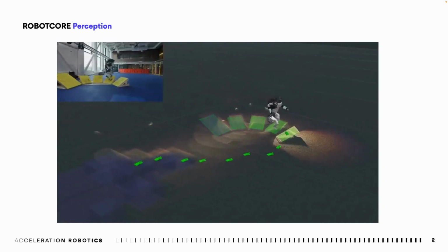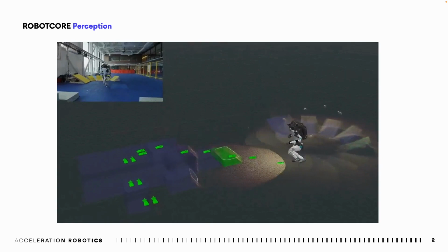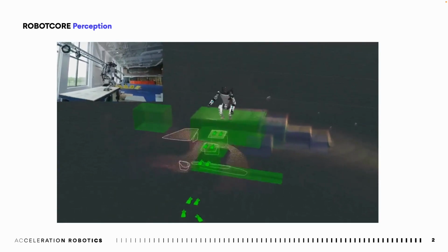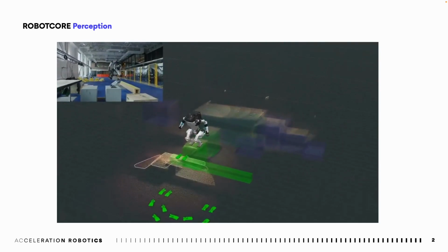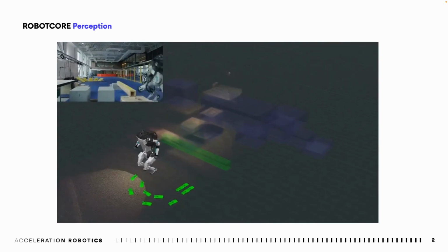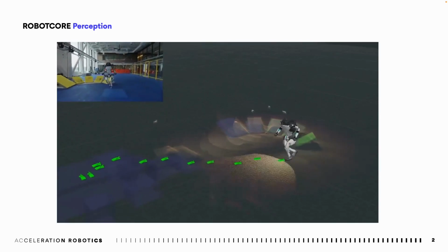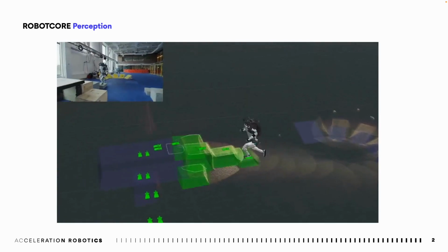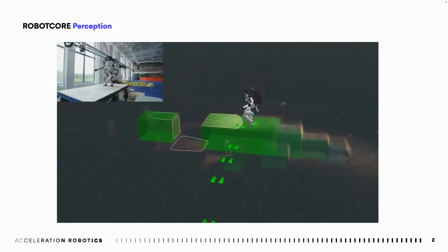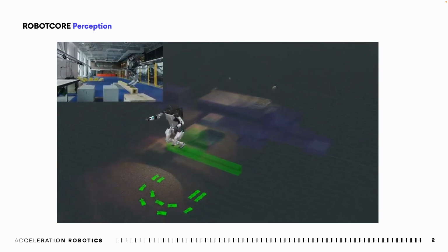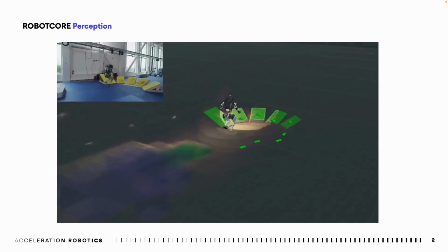Moving faster or with more dexterity requires faster perception computations. Atlas in the slide uses perception to identify, navigate, and jump around obstacles. Edge perception is key to navigate under environments that change, which are most in the human world. Atlas leverages a time-of-flight depth camera to generate point clouds of the environment at 15 Hz.